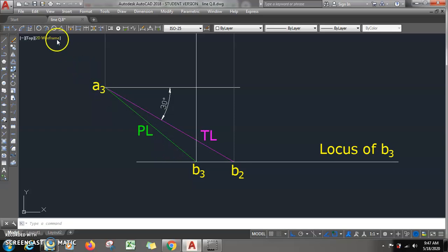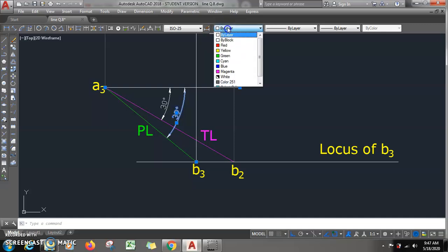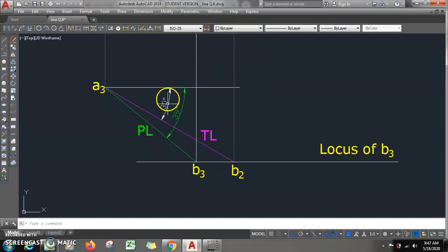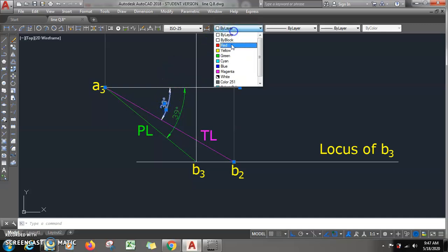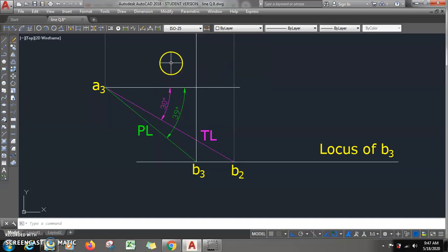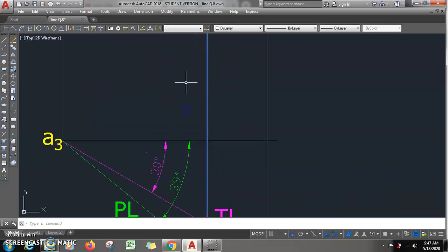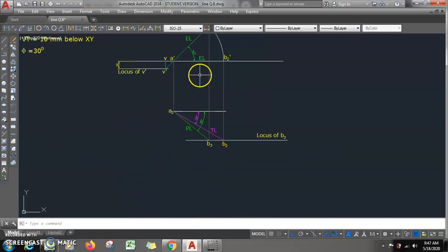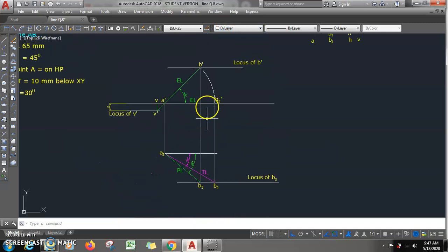This length is the plan length, and the angle of this line is beta. You see, the angle of the line is beta, and beta is found to be how much? It is 39 degree. This is the angle of the true length. Okay, so once we have this projector shown by a faint color line, only one thing is remaining. What? We don't have the true length at angle theta.